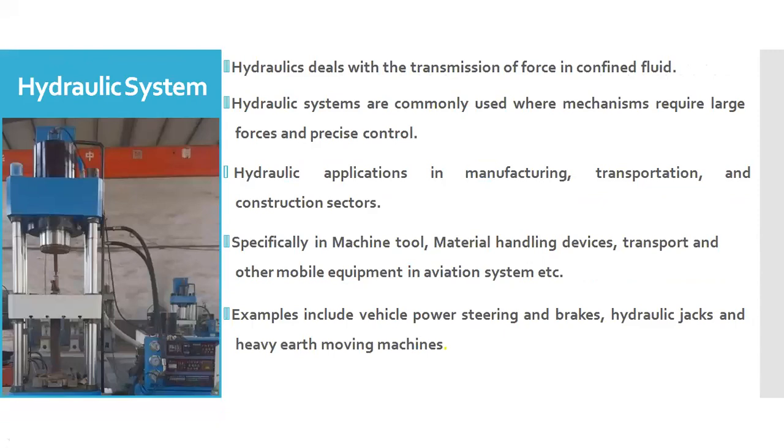Last time, yesterday I told you, and I showed you one video where I showed you the hydraulic pack. So hydraulic pack is basically a circuit of hydraulics, which consists of the different components of the hydraulic system. It is having the motor, it is having the pump, it is having the reservoir in which the hydraulic oil is filled up. Then that will be taken up to the different components, and according to the pressure that is generated in the system, those particular components will move.